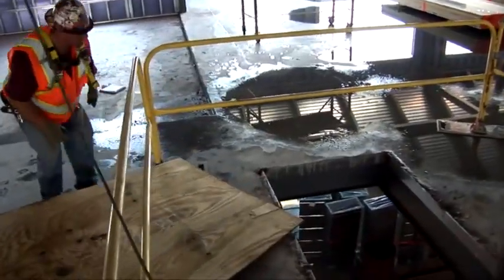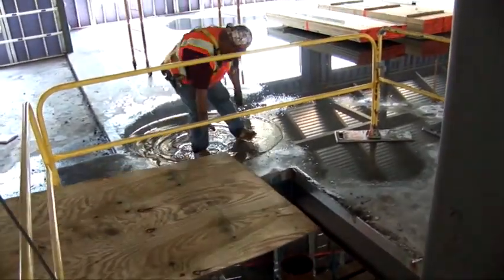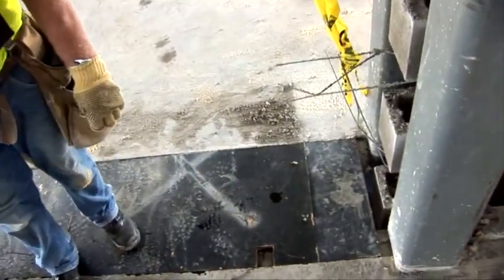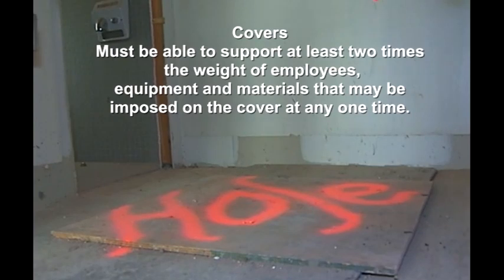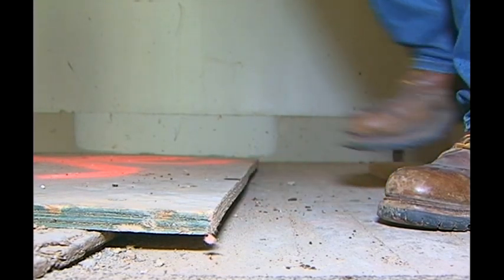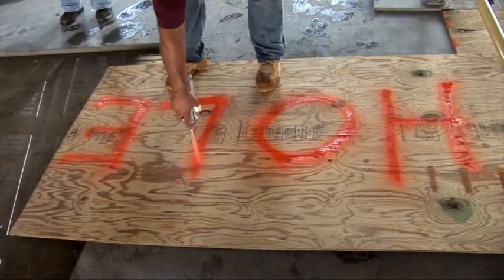Covers are another type of fall protection and should be used to keep employees from falling through holes in walking and working surfaces. They must be able to support at least twice the axle weight of the largest vehicle that might drive over the cover. It also must support at least 2 times the weight of employees, equipment, and materials that may be imposed on the cover at any one time. A cover should be well secured to prevent accidental movement and be marked with the word hole or cover.